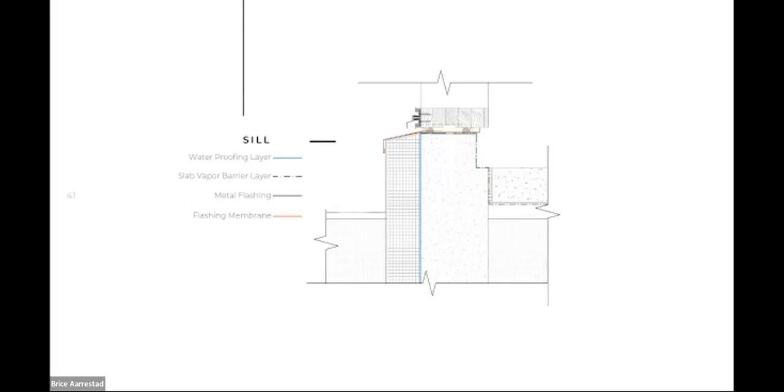Here again, I'm backing up one step. That hook that you're seeing on this gasket was the flashing flap that's part of the system. So when water gets into this cavity, it has a way out. It would weep out through those ventilation holes and drain out through that flashing membrane on the gasket.